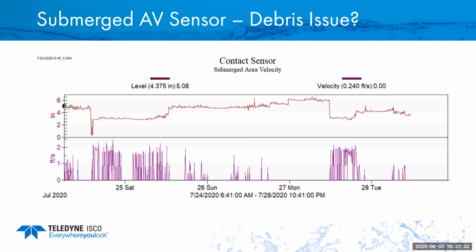Couple that with the appearance of the velocity data here, where in Flowlink, the analysis software, any errors in velocity have been set to 0, and we can see that there are a number of errors in this particular data. This would be an indication that this site needs some inspection to try to identify what may be causing the measurement phenomena we see here in this data. We could have some silt, sediment, or other debris built up that is impeding the measurement of velocity as well as impacting the level in this particular site.